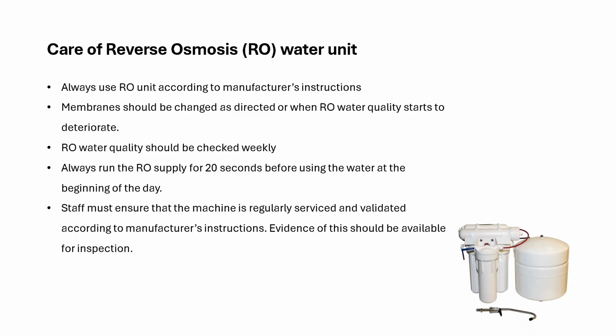So make sure you clean the reverse osmosis unit and you change the membranes according to the manufacturer's instructions. Always check for the water quality, and you can also run the reverse osmosis water for 20 seconds before using the water at the beginning of the day, and make sure that it's serviced.